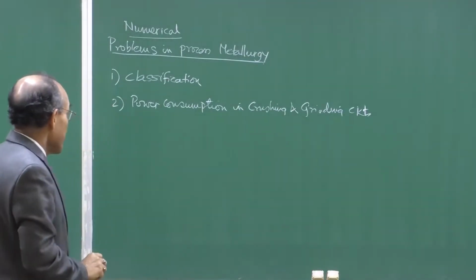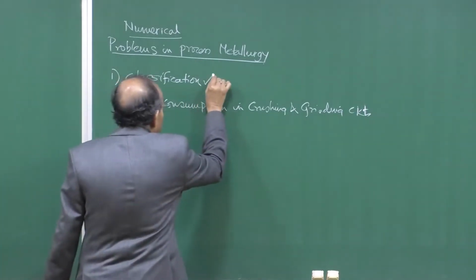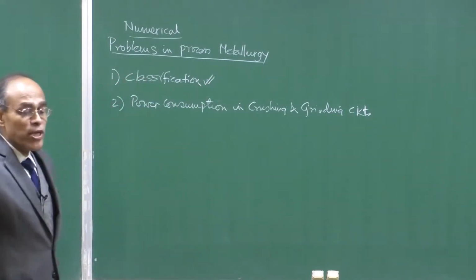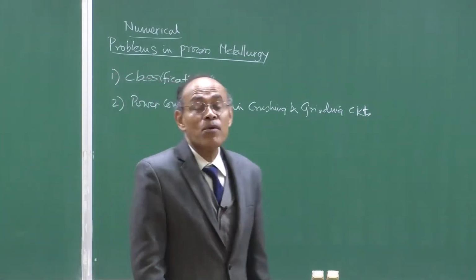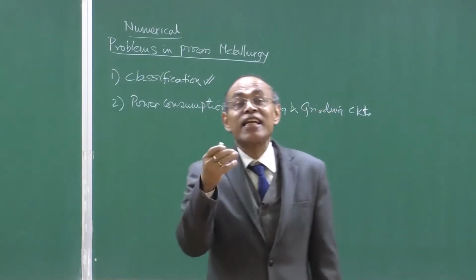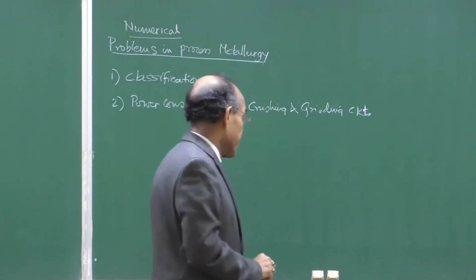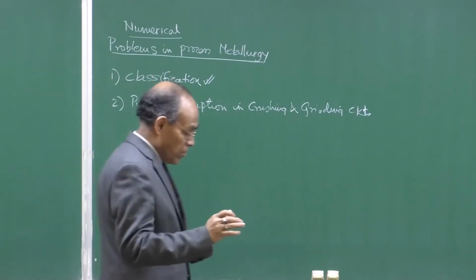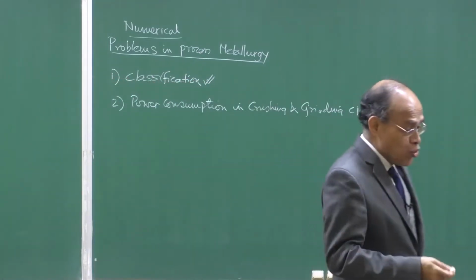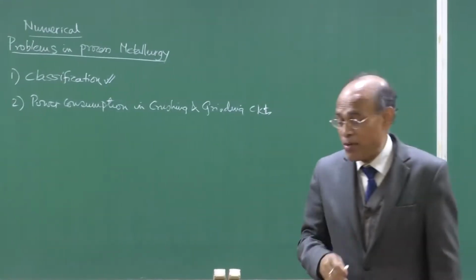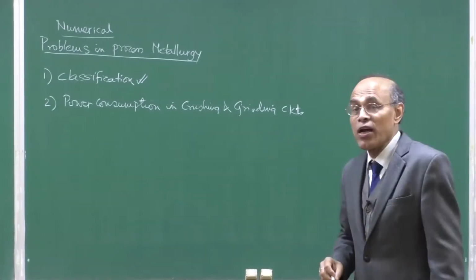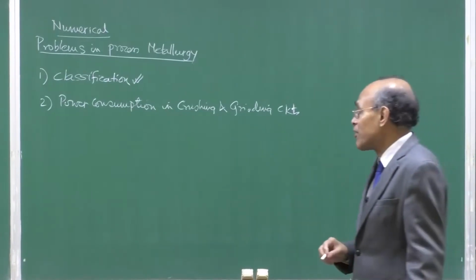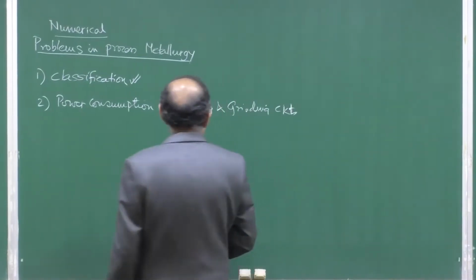as well as mineral engineering. Now, as far as classification is concerned, many of you may have heard the terms, for example, free settling and hindered settling, okay, and these are taught to you in your second or third year mineral engineering course with regard to separation of particles or classification according to sizes.